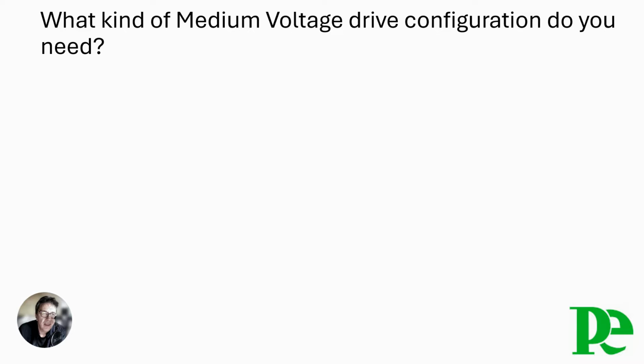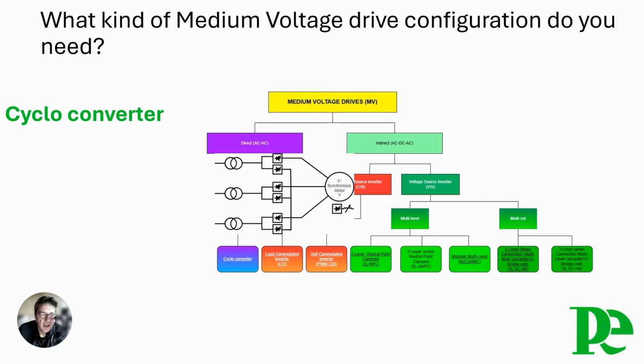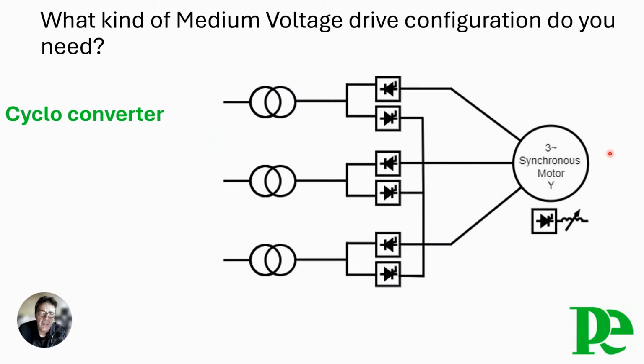A cycloconverter, often referred to as CCV, is in fact a frequency changer without any intermediate DC link. The CCV converts AC power of specific frequency and voltage of the mains to different frequency and voltage. It is basically built by 6 anti-parallel connected thyristor bridges.